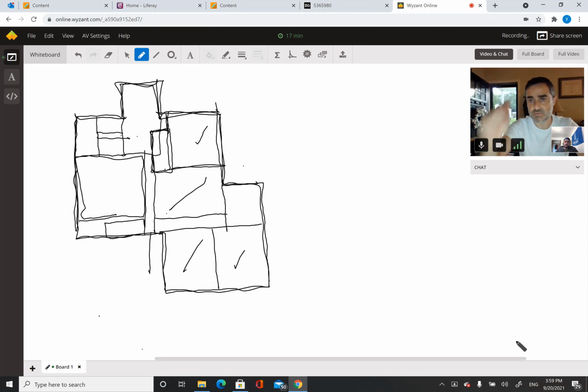Usually if it's a steel building, you've got columns, you've got beams, and then you've got a floor system. The floor system is usually a composite system, meaning it's made out of concrete and steel at the same time. With concrete, everything is concrete. You've got a column-beam condition, and you have some sort of slab system.